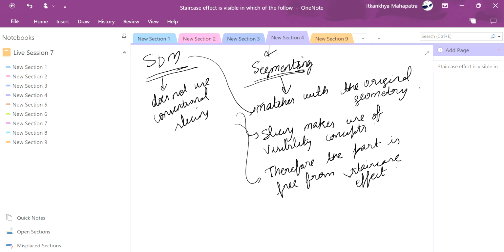So this is not about G code M code. It will automatically be generated, so you don't need to worry about that. It is there obviously. And regarding the temperature, depending on the 3D printer machine you are using, you will input the material. Since it is FDM, I'm going for polymers, like ABS or PLA.